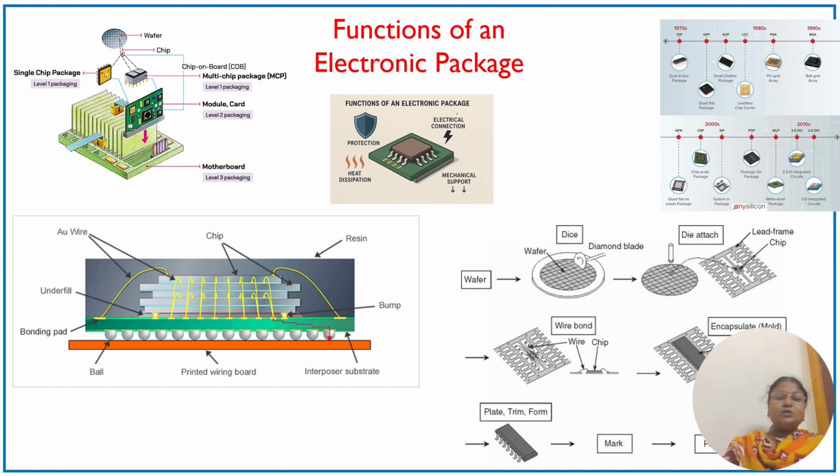So encapsulation has been done. Almost we have this plastic package. Also you can see a black color outer fitting for your IC. So this black color is for the heat dissipation. So automatically a heat sink has been inbuilt, and then we have plating, trimming, forming at last. We have a finished unit, which is your IC, which is packed. So this is the packaging of your IC.